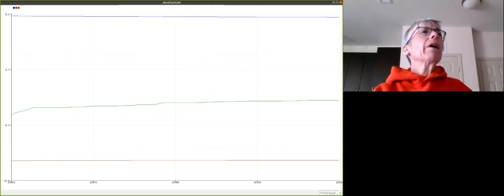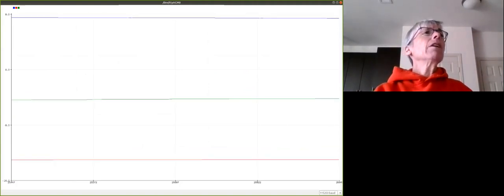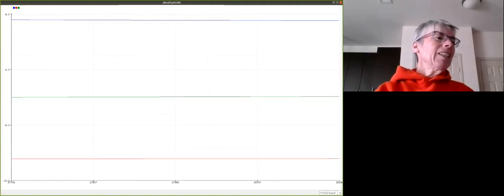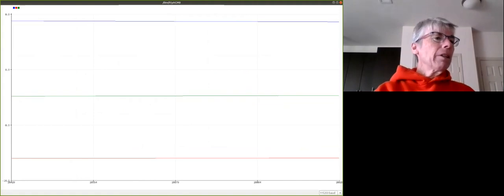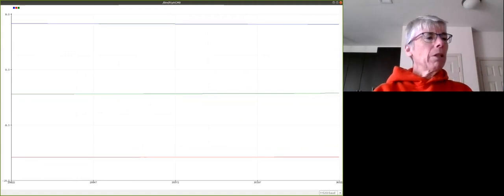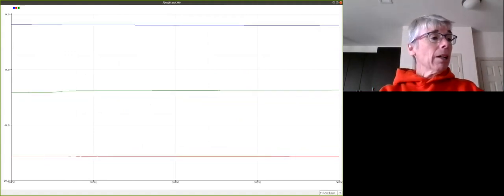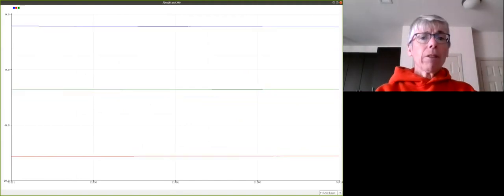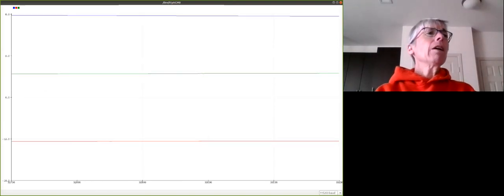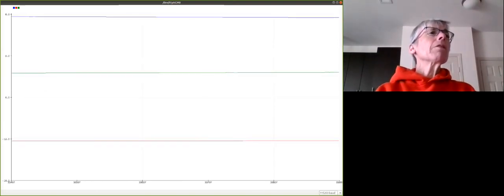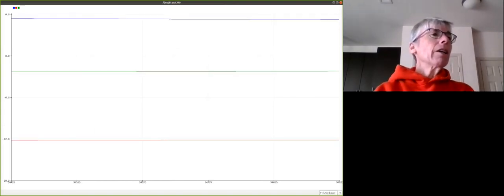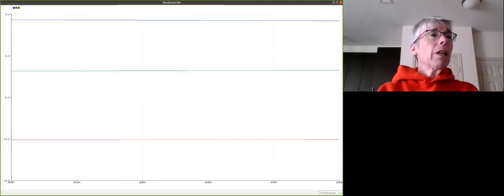And let's see if we come back to 0 after a while. And you can see I'm not coming back to 0. Something thinks it's about 7 degrees. And actually, I don't know if my actual orientation could be 7 degrees off. What I should really do with an experiment is use a piece of tape or something to outline on my desk the orientation so I could put things back in the same way. But I suspect that this is our yaw angle, and yaw can't be measured very well simply with a gyroscope.